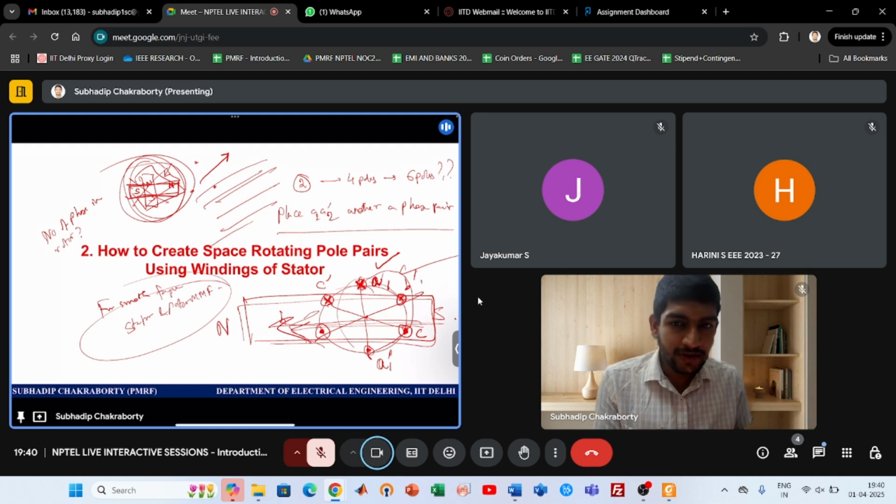We are talking about the adjustment of poles made by the rotor virtually to equalize it with the number of poles in the stator itself, because of the general theory of rotating machines. By the general theory of rotating machines, stator and rotor MMF should be stationary in space with respect to each other, for which the rotor has the constraint to adjust itself to the number of stator poles. That much understood. But can you tell me about the number of phases in the rotor?